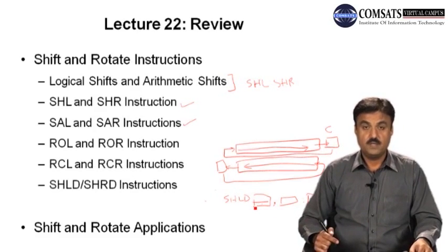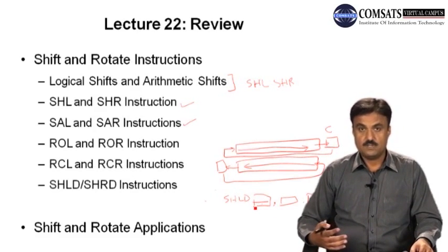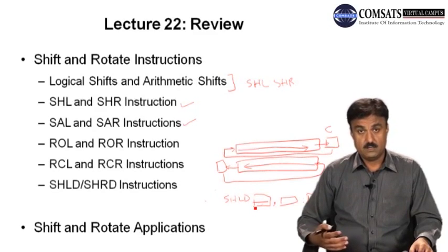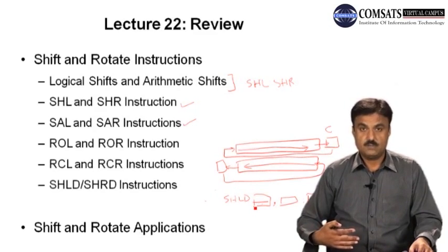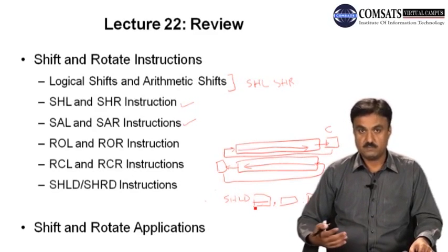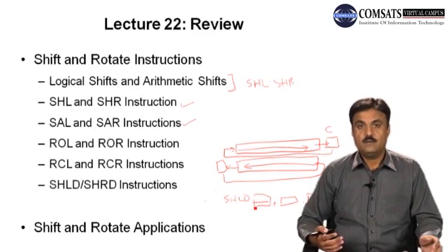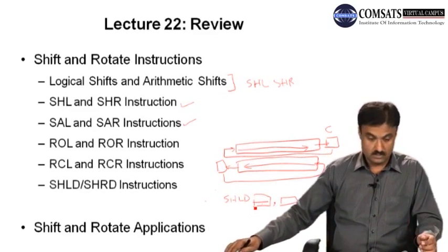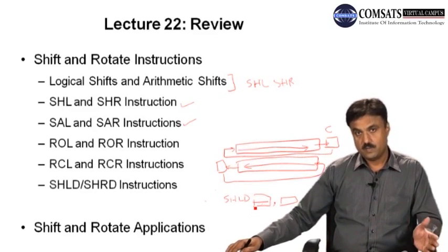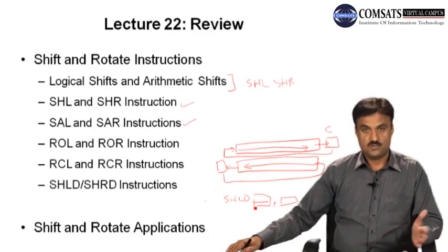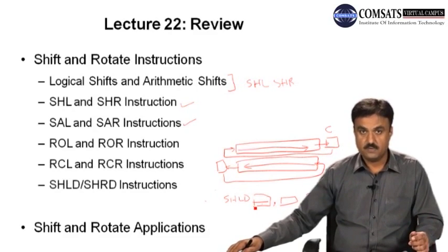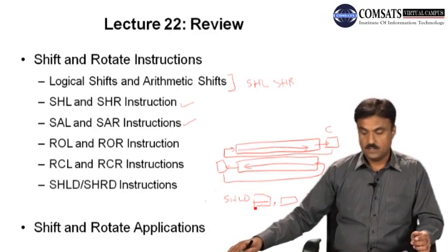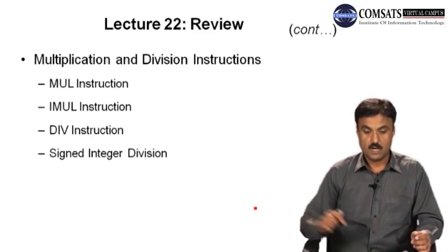Then also, in case we want to display the binary values inside the register, whatever values are inside the register, we want to display the equivalent binary. So we shift left or right and monitor the carry, whether the carry is set or reset. For that purpose we use a string array, and in this string array we replace elements with either 0 or 1 based on the value of the carry.